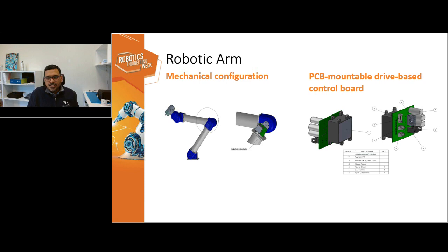The advantage of this is also for maintenance: you're able to replace just the drive, the motor and the controller on each axis independently. When you swap them out, it automatically detects the new one, assigns all the parameters to it, and it takes the identity of that axis controller. This is a robotic arm, which is very common in the surgical robotic space.